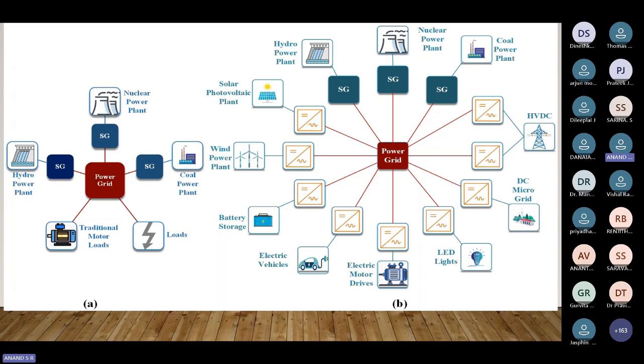Now we have a lot of electronic loads, which means a lot of pollution, electrical pollution, is being put into the grid. So we need to correct that also. That required installation of STATCOMs, power conditioners, power flow controllers, and all these things have now become a requirement. And most of these things have become reality in the Indian grid also.